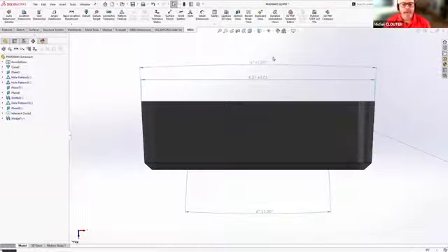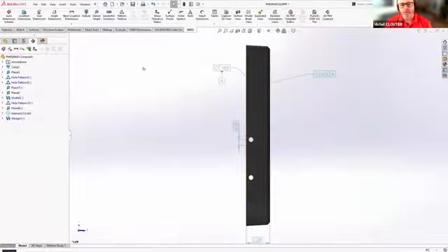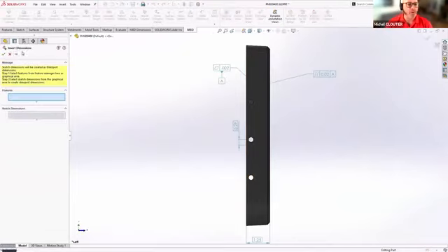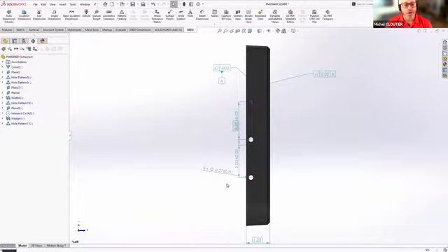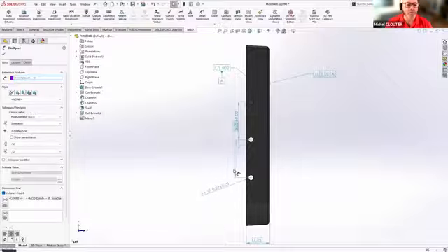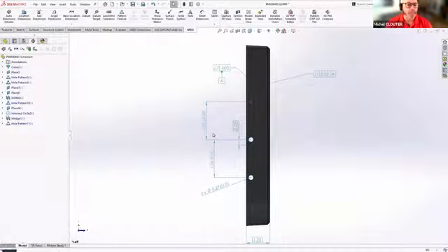So as I reposition that, the other thing I want to discuss is that many of those dimensions that I want to annotate in 3D already exist in the form maybe of a sketch or a feature dimension. So starting with 2025, we can actually repurpose existing sketch dimensions or feature dimensions in my 3D annotation. So I don't need to recreate all of those dimensions. If they already exist, I can simply repurpose them in my 3D annotation.